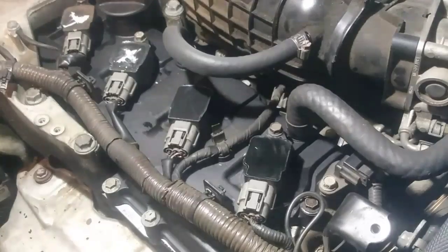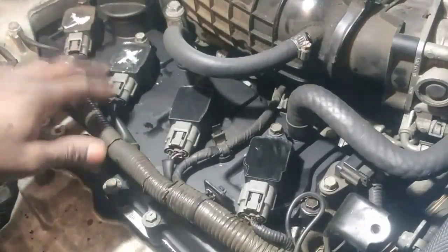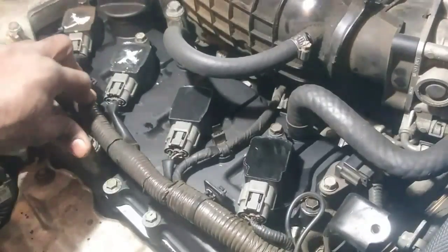The startup was cold. The combustion chambers were cold. It's leaner and it's harder for that spark to arc. That's why we got what we got. We got a misfire at low RPM, that's if you're able to catch it then. Again, this vehicle, when it's warm, would run fine at idle, but will misfire up top.